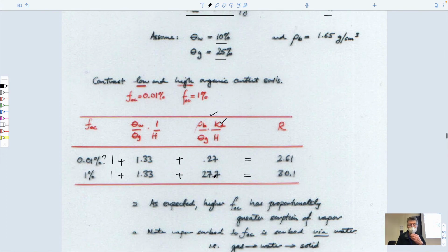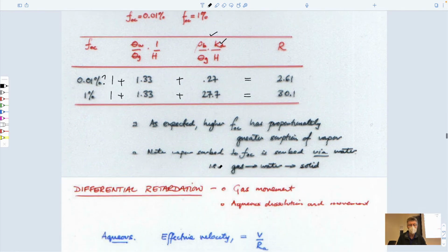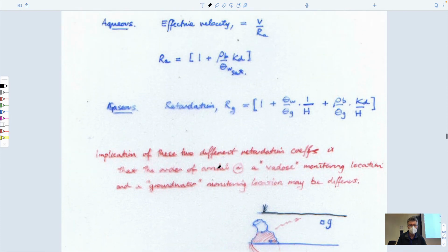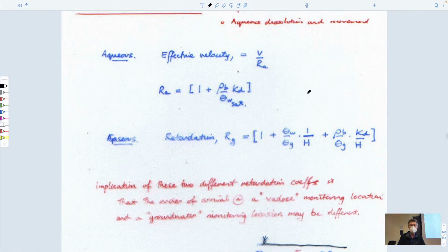The other thing that comes out of this is also that for different compounds, you may end up with different rates of retardation. And so you know that when we were talking about retardation, we looked at the relative rates of concentration traveling with distance. And just for diffusion, we said that length is equal to diffusion coefficient over time times retardation.